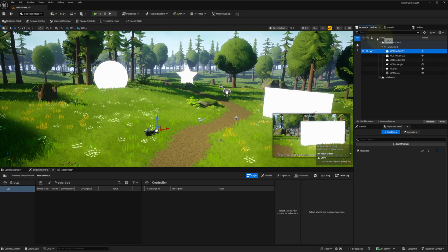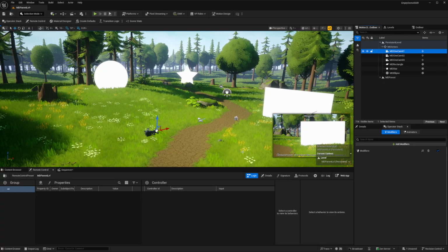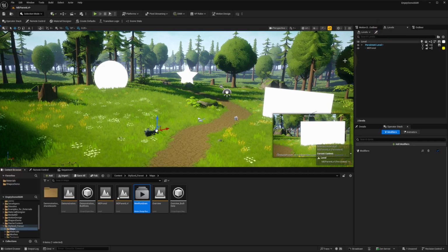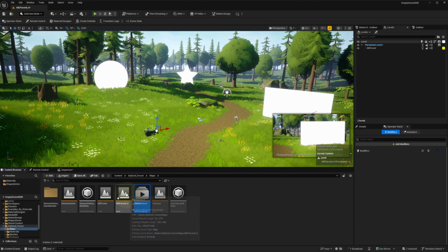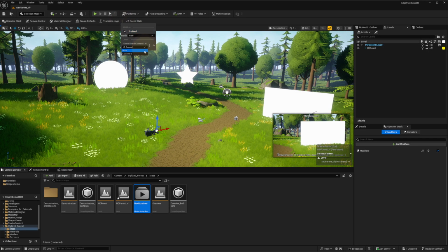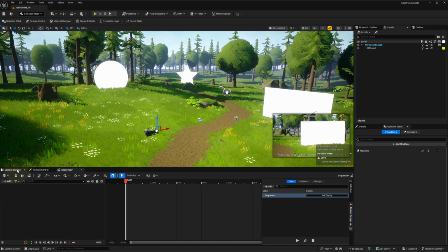And so the final thing about this particular setup, particularly since this environment's pretty involved and has some foliage, grass and everything, what I did was set up a parent level, and that is MD parent level, and that is the overall container that has transition logic enabled. And I just selected one of the defaults like L3 General just so that it has a layer name so that transition logic will work. I did not set up any sequences whatsoever, so there's nothing up my sleeve there.